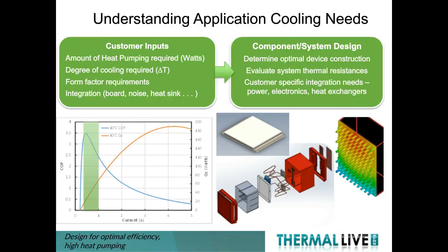Right, so it sounds like the bottom line there for our listeners is some typical control mechanisms where you just turn on and off, which both with pulse width modulation, PWM, turning on and off a high voltage means you're running the thermoelectric at a low efficiency point, whereas running it maybe more on time, but at a lower current, let's say, allows for a more efficient operation of the device.